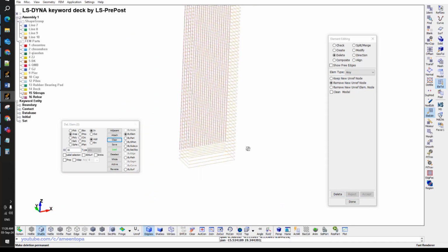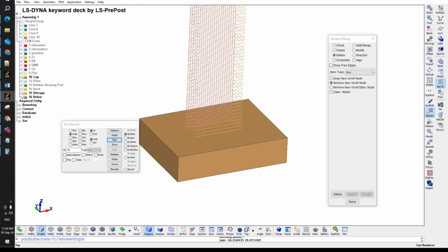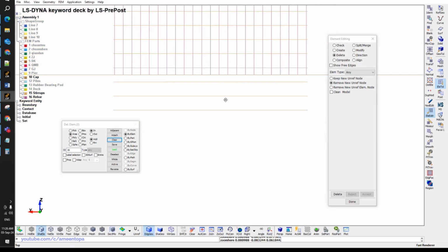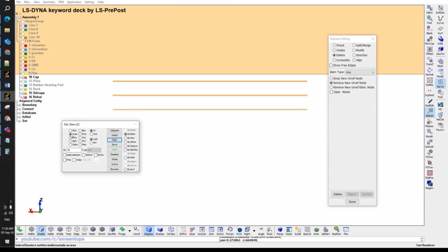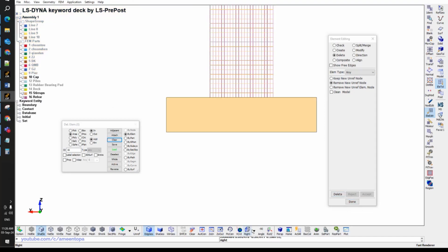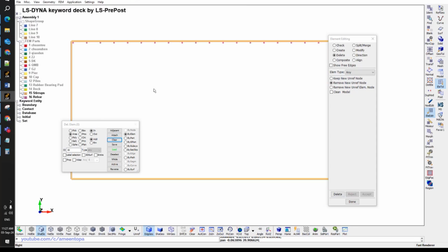Okay, now we are almost done. From the right view, since we are deleting, I will delete these extra ones by elements, area, highlight this area, elements inside the area will be deleted, accept, done. Okay, now again go to the top view. Okay, it's here, hide the cap. Okay, now I can move this to the other side.